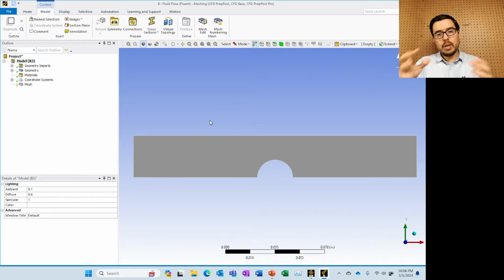When we start having more irregular geometries, the number of nodes and elements and how we refine and have a sufficient number of elements and nodes becomes a little bit more arbitrary and a little bit more artistic, quite frankly.